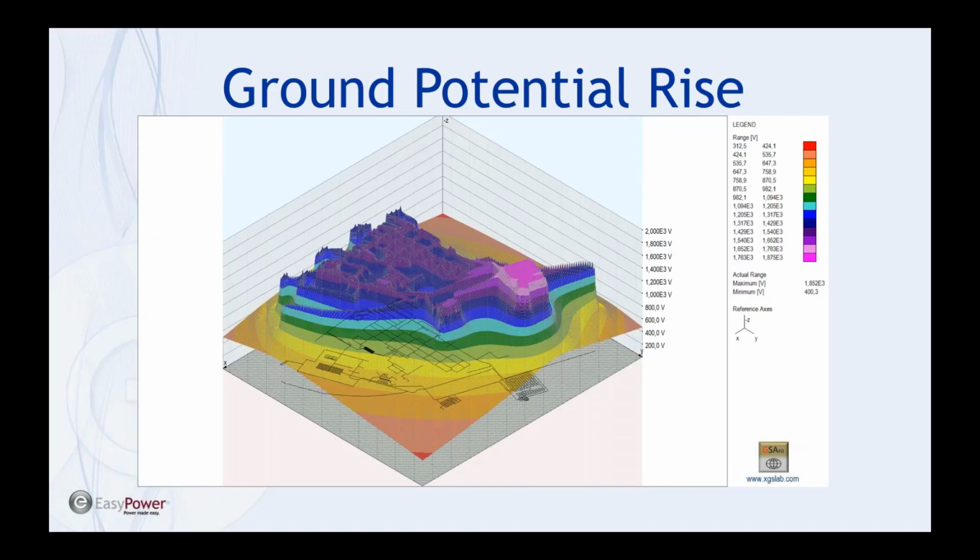For a visual representation of ground potential rise, we have a large grid shown here. In this image, there's a topographical overlay of GPR shown floating above the buried grounding conductors beneath. This is a large, complex, connected grid. The fault that is causing the GPR is likely located in the pink area on the right, the area with the largest GPR. You'll notice that other connected portions farther away also have elevated GPR, but to a lesser extent.